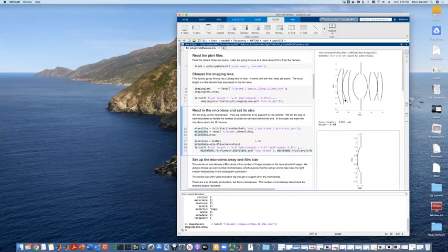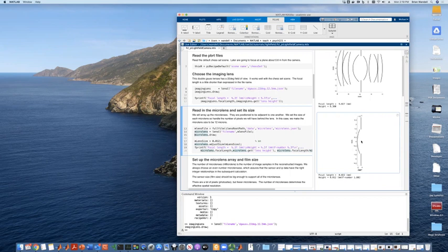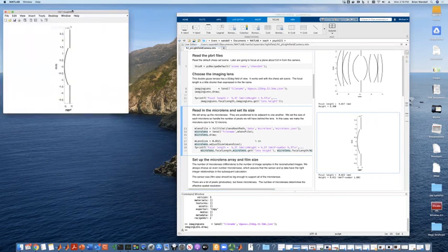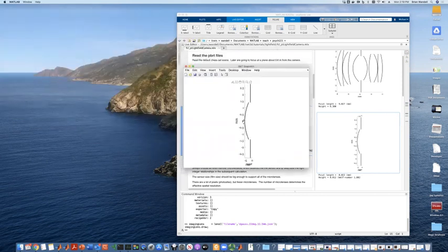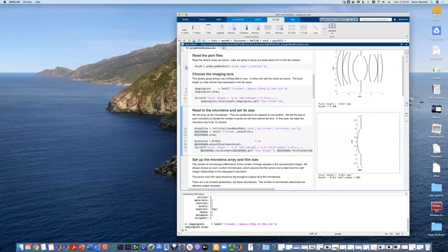And this is a pretty standard lens, the double Gauss lens. This one has got a focal length of about 10 millimeters. And this little micro lens here is really, really tiny. Let me make it bigger. You can see it's really small. This is in millimeters, and this thing here, when it first comes up, has this 10 to the minus third millimeters. So you're kind of looking at microns over here in terms of how big this thing is. So it's a really small little lens we're going to put on top of the sensor surface.